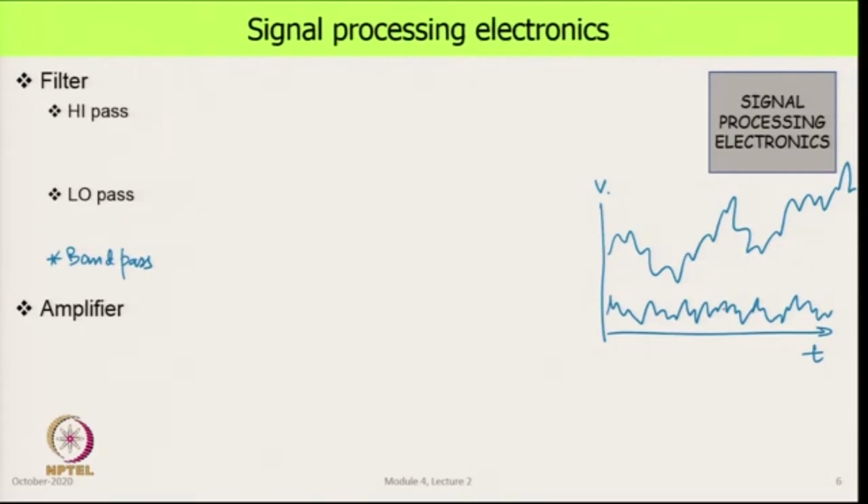So, this sort of signal, each one of these wiggly things, can be broken up using a Fourier transform, and this will tell us how much strength there is in the signal at different frequencies. So, here we put frequency and here we put the strength, and you get that at this frequency the strength is this much, at this frequency the strength is this much, here it is this much, here it is this much. So, depending on the nature of the signal, we will get that many number of these lines.